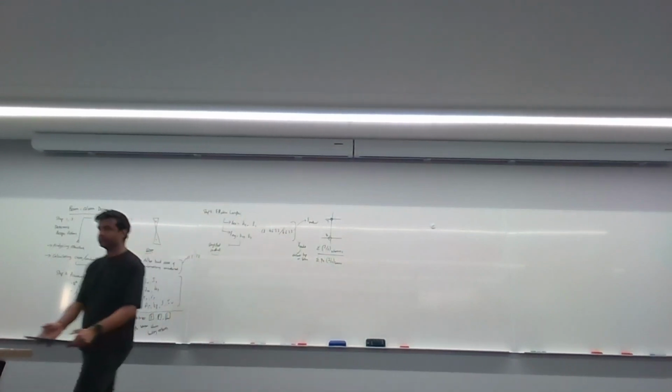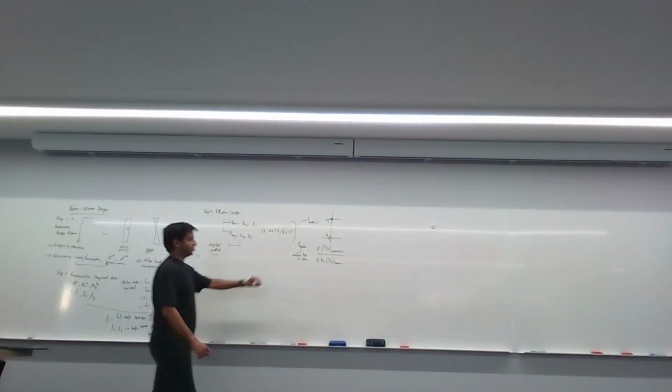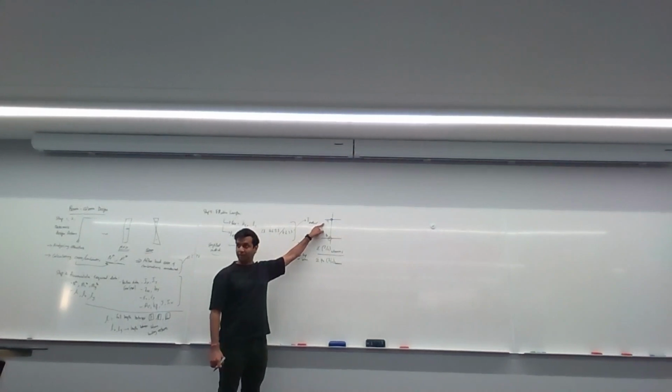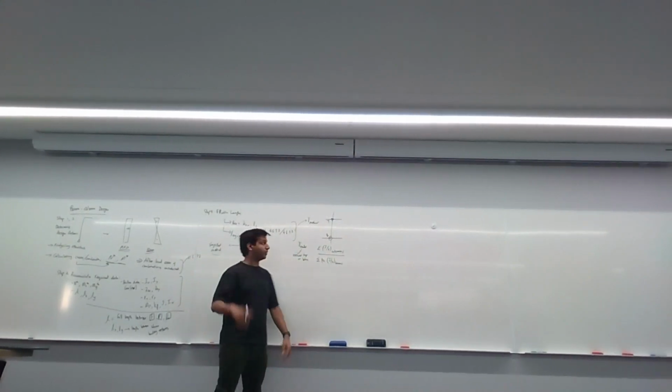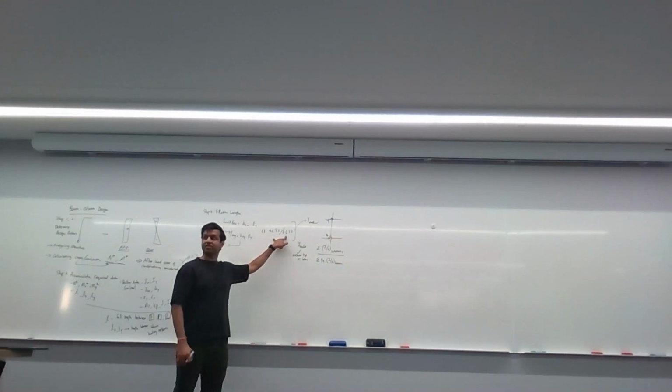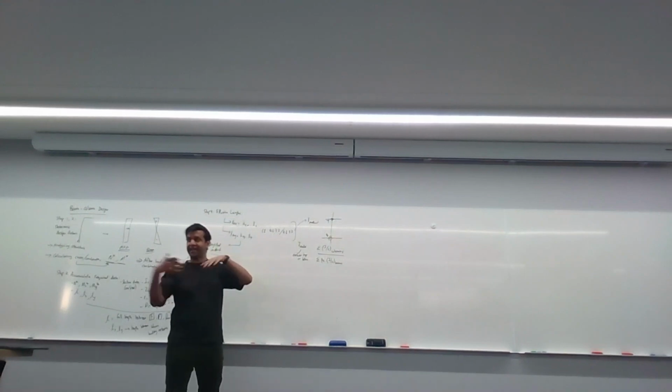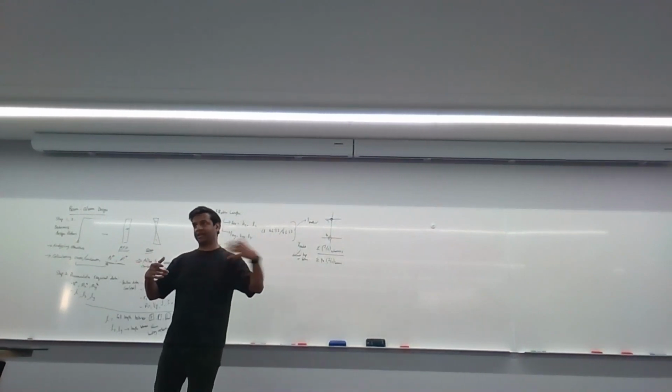You do this for the top node and get your gamma top. You do this for your bottom node, get gamma bottom. Once you do that, you use these clauses to calculate what KE is, and that'll be KEX. Then you do the same thing in the y direction to get KEY.